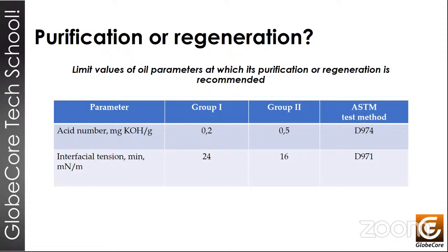So it's always important to take samples of transformer oil. That allows us to find out what is happening inside the transformer. A reasonable recommendation would be to make a complete analysis to identify the problems that exist. So when we detect some changes in the oil under normal operating conditions, we can take appropriate corrective action, and that will extend the life of the equipment, causing the least amount of wear and tear and damage. So understanding the changes, the reasons for these changes, and having the ability to stop the degradation process are all important to extend the service life of the transformer, and so we can take predictive action rather than just corrective action. Okay, next slide, please.